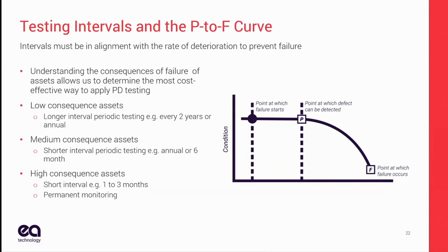Or how often should I be testing for PD? No one that knows anything is going to give you a definitive answer for that. It depends on your criticality. It depends on how long the PD is going to go from the start of the PD to the detection point to the point at which failure occurs. We can't always predict that because we haven't taken the system apart to see how fast it's going to progress.